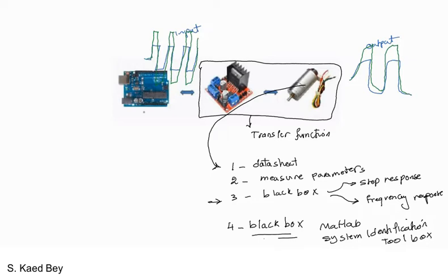Before we move on to Matlab and estimate the transfer function, we could check the linearity of the system. So perhaps we could use 200 RPM as a maximum value, and we could use the initial one as 100, because I know that the motor could saturate at roughly 300. So 100 to 200 is roughly within the operating range for this motor.